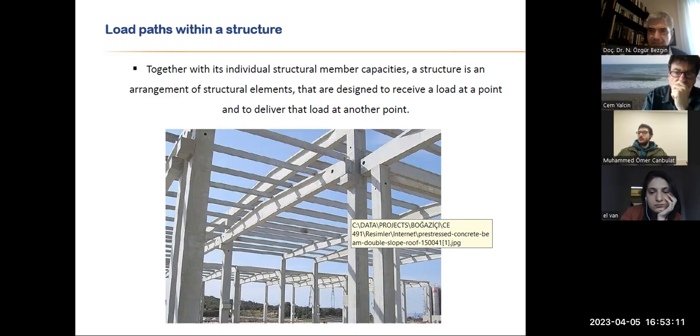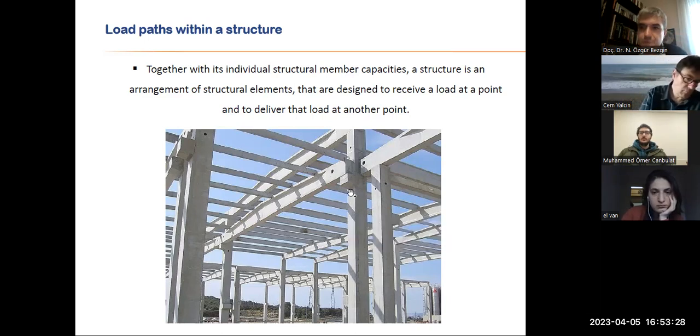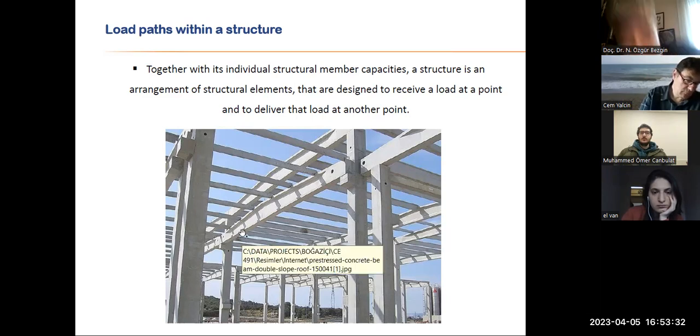If there's shear, you ask the question, how am I going to respond to that shear? If there is a moment, you ask yourself the question, how am I going to respond to the moment? So you can define it explicitly. Nothing is buried under concrete, under the free-flowing concrete. Everything has to be responded to. But if it's not responded to, then it will fail from the joint. Sometimes in earthquakes, there are pictures of prefabricated structures where the elements are all over the place.